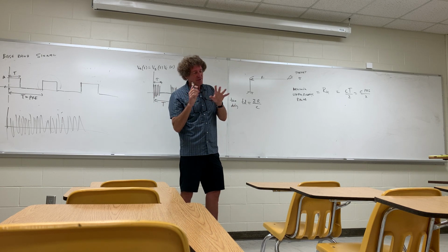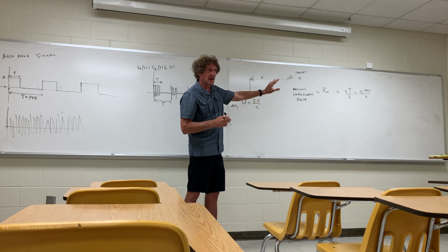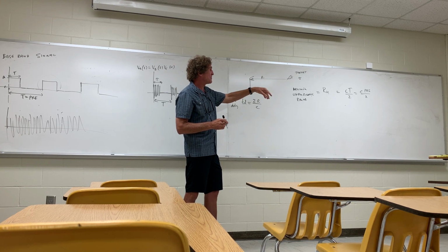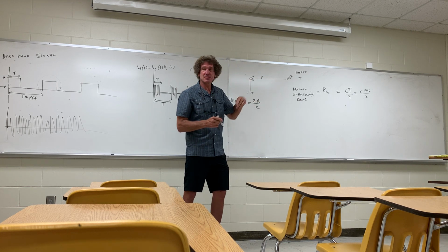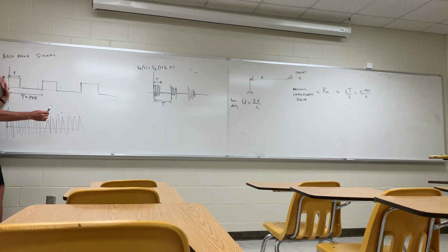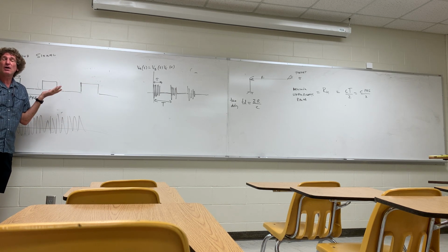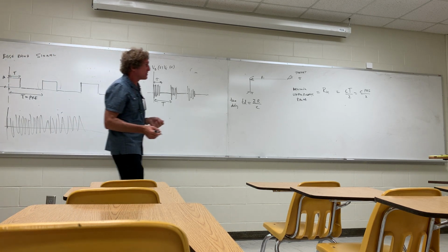There's a lot more to it actually, but this is the basic concept. So this maximum unambiguous range tells me where I should be on the cusp of being able to detect the signal when it returns. You don't want a situation where I'm able to detect reflections from targets when the time delay is from here to here, and I don't know where that target is. I've got 3 pulses that could have caused that echo. Follow me? That's some of the things that go into engineering a radar.